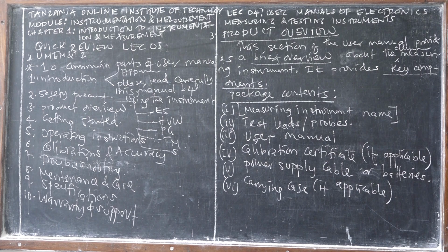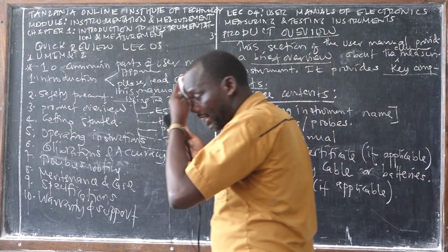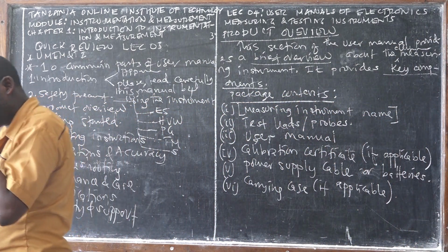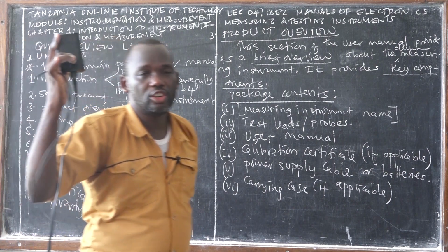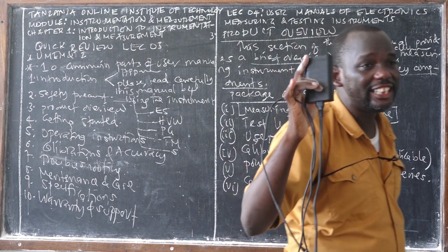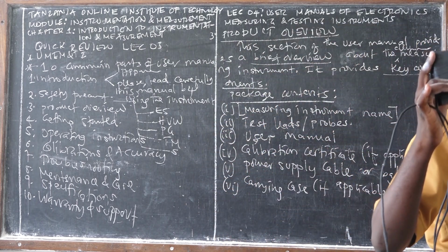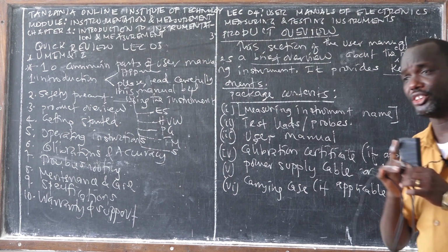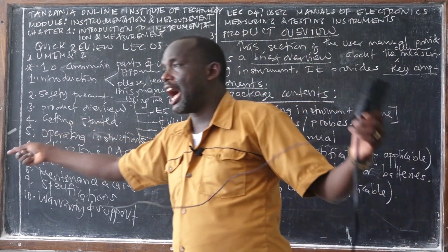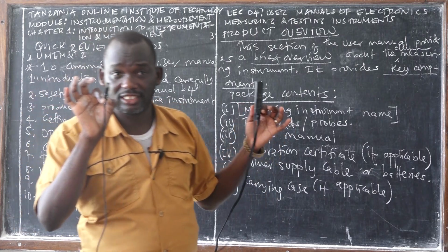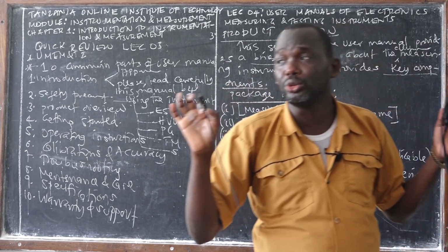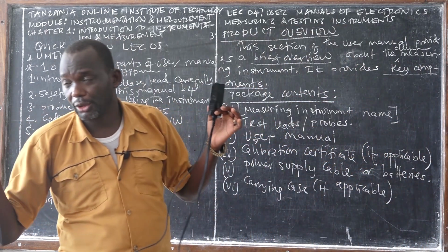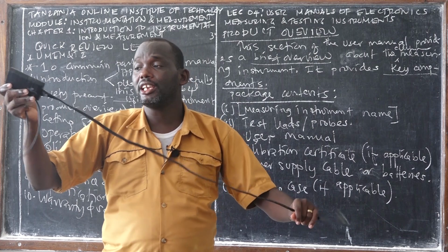The response is simple. Because the input of this computer adapter is what? AC. But this part, this black box or black case, contains the switched mode power supply to convert AC into DC. So the output of this computer adapter will be DC. For most laptops, it ranges from 17 volts up to 19 volts. Are we together?